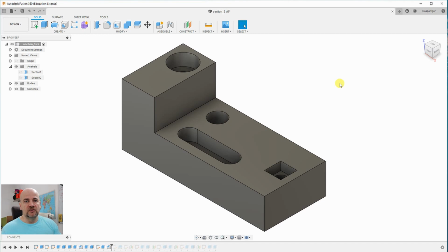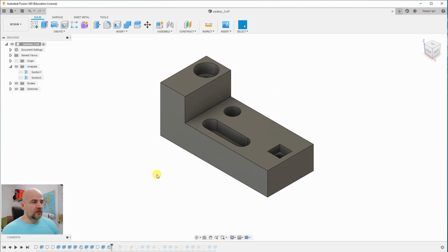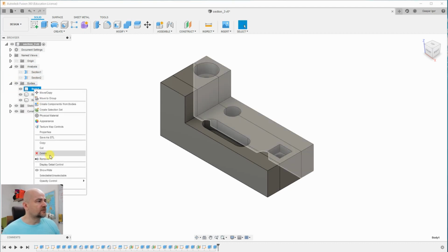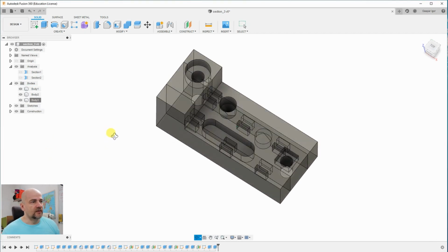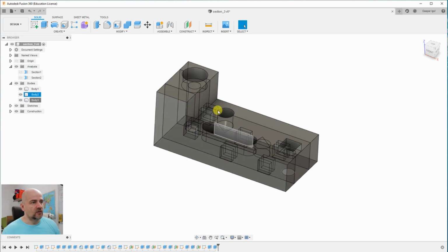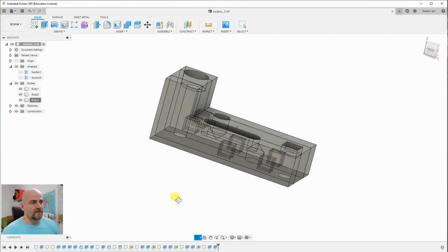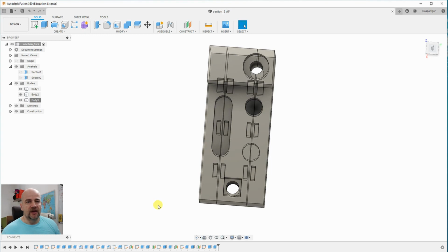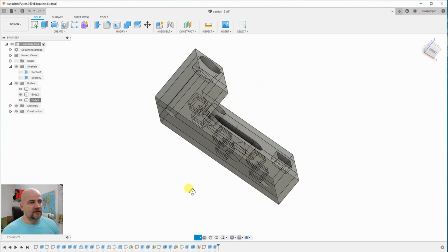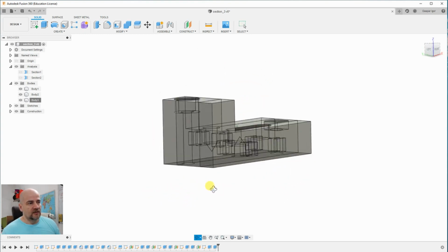Okay, so in Fusion 360 so far this is one body, one object, but then again I use a split tool to create 3 different objects, and then I have to insert those holes. Let me show you in a transparent object. So now you can see those squares, these are holes for the magnets. Here you have 6 pairs of magnets which I have to insert.